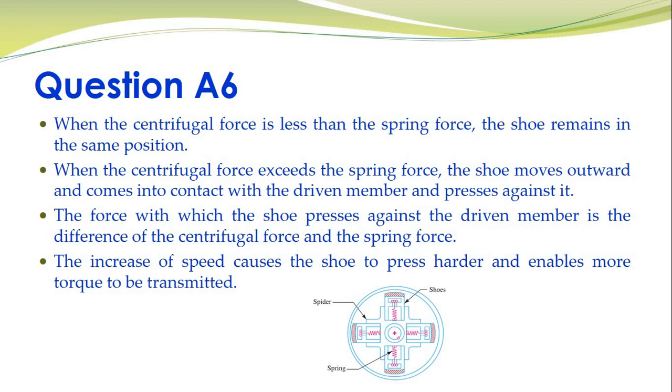And once the speed starts to decrease, the shoes will again start to move inwards, because the spring force is now becoming larger compared to the centrifugal force. Once that happens, the shoes will lose contact with the driven shaft, and what you'll notice is the driving shaft will rotate. However, the driven shaft will remain stationary.